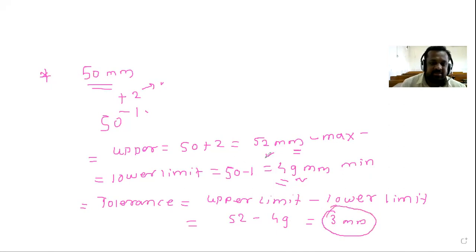म्हणजे आपल्याला suppose we have to manufacture or produce this shaft of 50 mm. म्हणजे जर आपल्याला हा शाफ्ट मॅन्युफॅक्चरिंग करायचं असेल, प्रोड्यूस करायचं असेल, तर आपण किती mm व्हॅरिएशन घेऊ शकतो? 3 mm व्हॅरिएशन जर आलं, प्लस मायनस 3 mm, we can call it accepted. This is called as the tolerance. Understood?